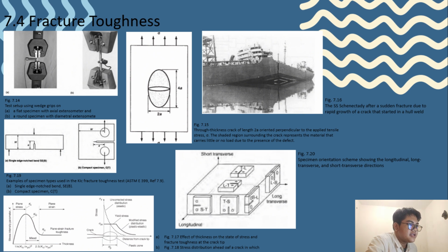A similar analysis can be performed to evaluate the critical tension stress. And as we can see in figure 7.14, the test setup using wedge grips: in A, a flat specimen with an axial extensometer, and B is a round specimen with a diametral extensometer. Then we get figure 7.15, a through-thickness crack of length